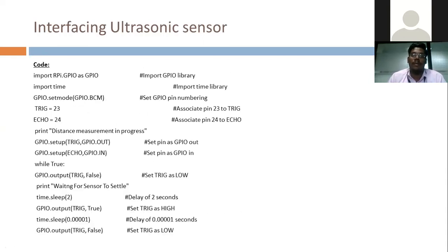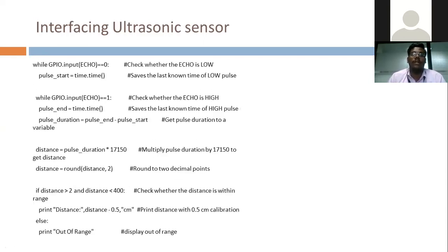While sending this, I am also measuring the time based on the value of the echo pin. Whenever the echo pin receives 1, the pulse has been received. Whenever it gets 0, the pulse has not been received. Whenever the trig pin triggers the pulse, I start the time and store it in a pulse start variable. Whenever the pulse is received, the echo pin changes to 1 and the time is ended. I store that time value in pulse end.